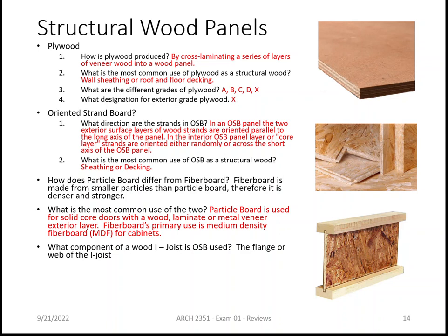What's the difference between particle board and fiber board? Does anybody remember or no? They're very similar. Okay, they're very, very similar. One's a pretty poor product. Particle board is made the same way fiber board is made. The difference is in the size of the particles.